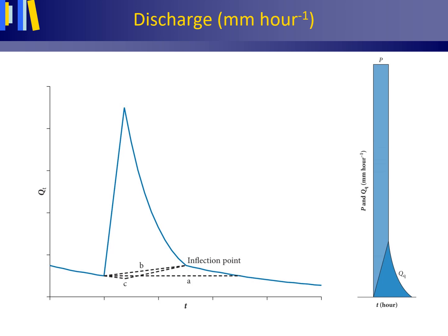Importantly thus, a discharge presented for instance in millimeter per hour is not a velocity, what it may seem at first glance, but a discharge in cubic meter per hour adjusted for the drainage basin area by dividing by the total drainage basin area in square meter and multiplying by 1000 millimeter per meter.